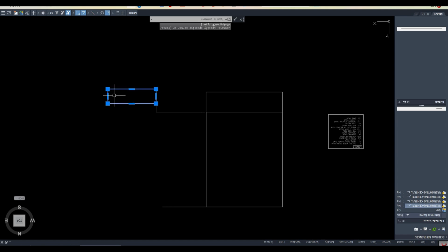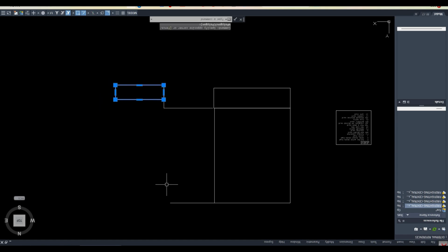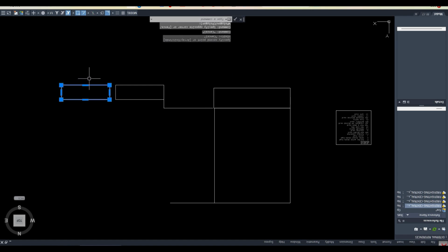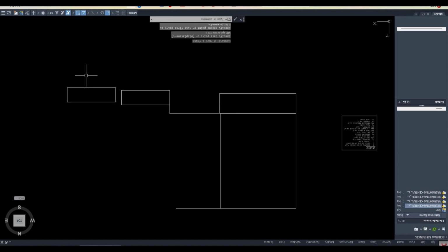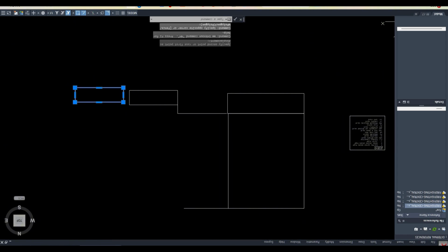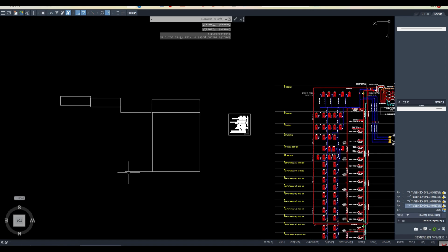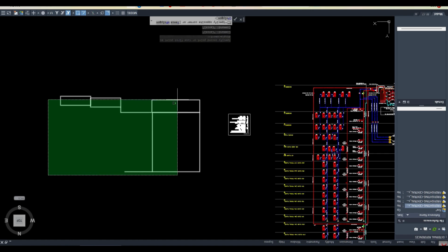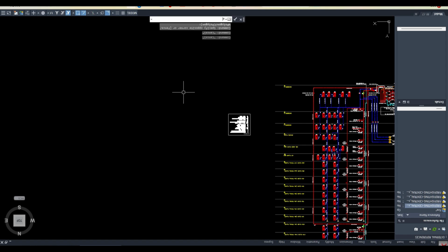But this grade level is also not just whatever grade level you can see. In a building we can have multiple kinds of roads which have multiple slopes. So whichever grade is at the lowest point, from there we will count till the roof level. Okay, so this is how we count the height of the building. So this confusion is gone.